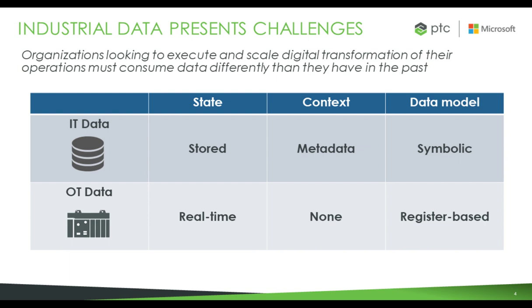But there are many legacy controllers. Again, Modbus is a good example, where everything is still register-based. That goes back to the example before. You need to know that registers 40,000 to 40,003 have been configured by the controls engineer to hold a variable that's a long data type. Because if you just read register 40,000 as a word, it's not going to mean anything. And of course, all this refers to directly connecting to a Modbus device. There are many tools out there that make this easier.